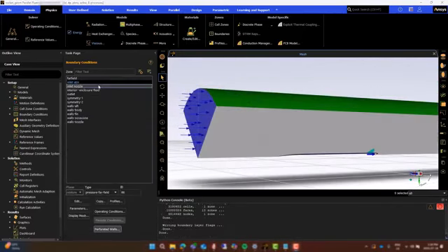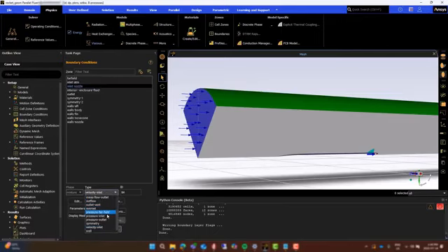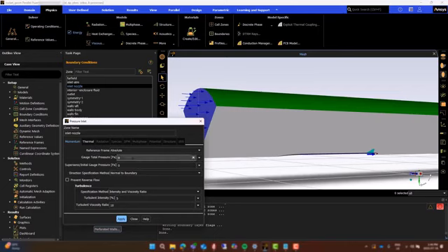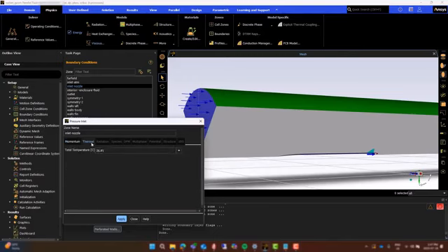We'll now set the boundary conditions of the nozzle inlet, which corresponds with the discharge of the combustion chamber. Thus, we'll use a pressure inlet condition, assigning the total gauge pressure to 4 megapascals, and the initial gauge pressure just slightly lower to 3.8, assigning the thermal boundary condition to 3326 degrees Celsius.